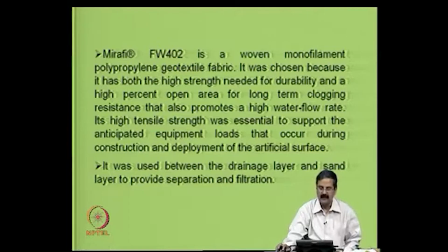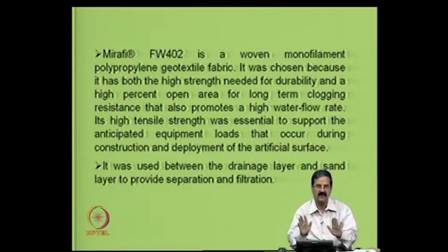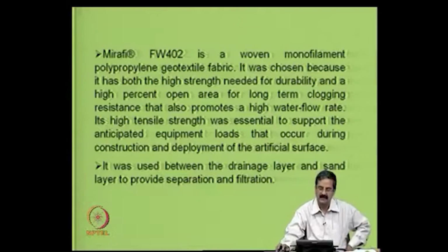Like the other day I was showing you the difference between a conventional filter and a geotextile filter. The water flow is a very important variable. Porosity is one thing, but water flow is another thing. So, you may go for a highly porous system, but then it should also be stable. So, there are some issues. That is the reason why geotextiles are excellent as filtration materials, and its high strength was essential to support the anticipated equipment loads that occur during construction and deployment of the artificial surface.